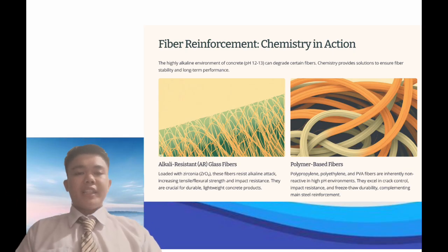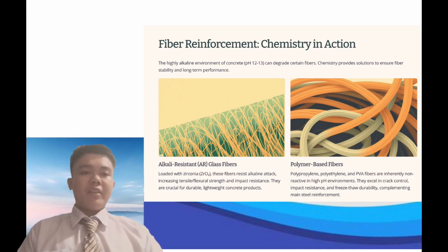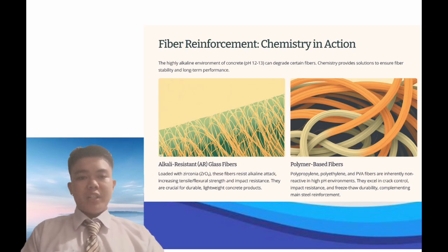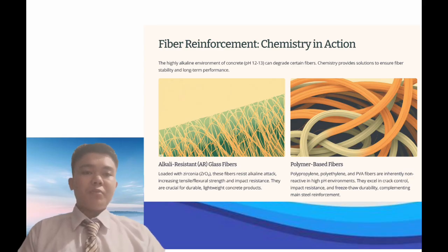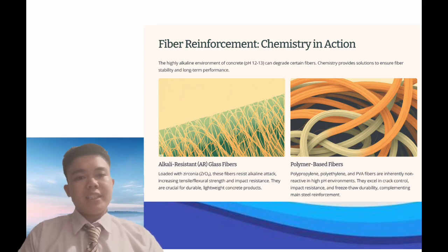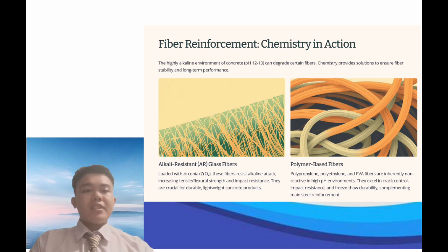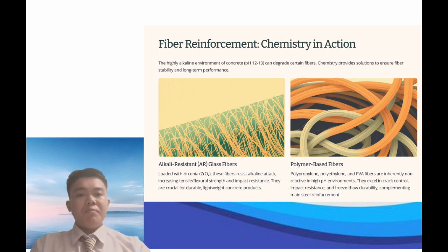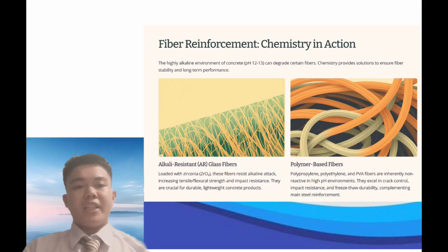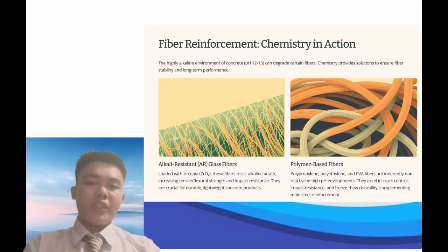These fibers are non-reactive at high pH levels, flexible and durable, with the ability to preserve tensile qualities even after long-term exposure. Because these fibers do not degrade, these chemically designed fibers can continue to function throughout the life of the concrete. These fibers essentially serve as a first line of defense, ensuring the chemical integrity of the concrete from within.